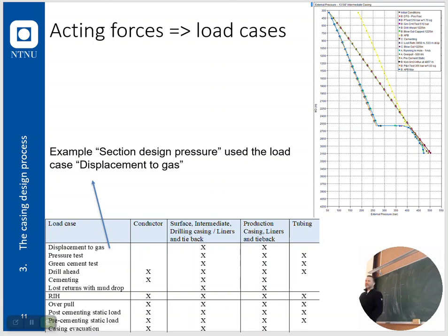Running hole. Horsepower on the rig, and your string up. How much can you pull? You guys have probably calculated string weights, right? And when it comes to drill pipe, it's nothing. Casing is the heavy part, right? If your casing is stuck, how much can you pull?